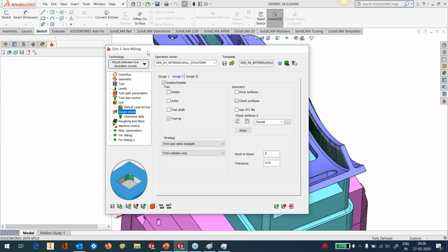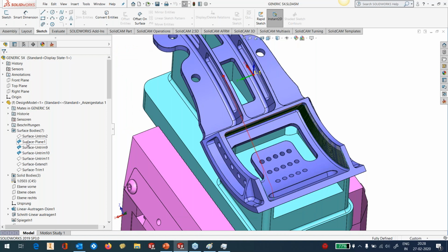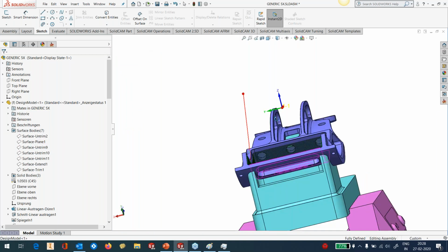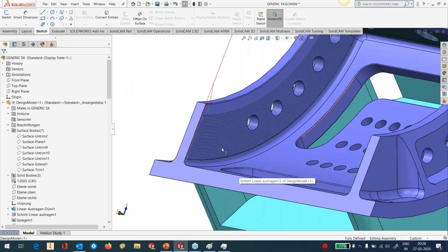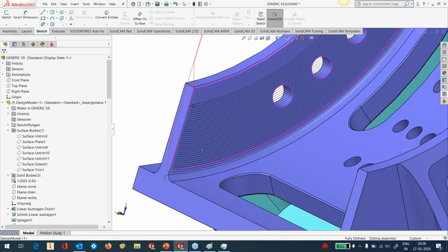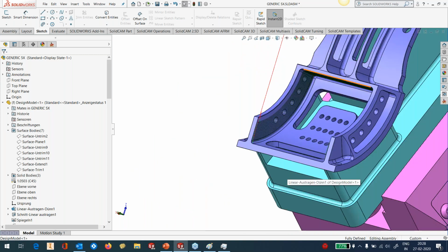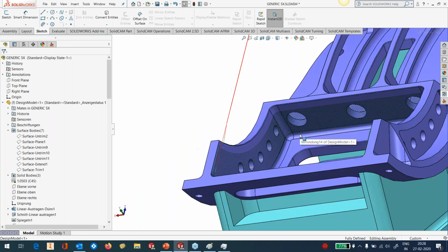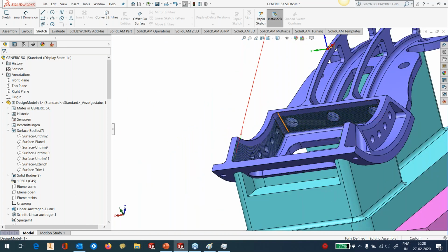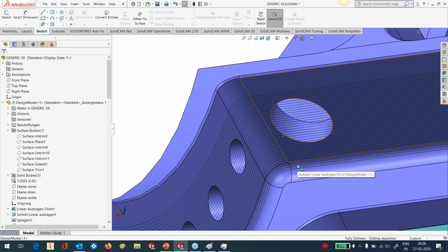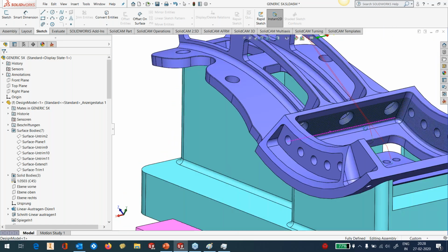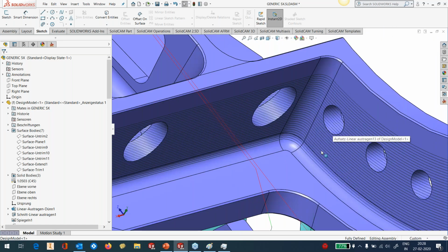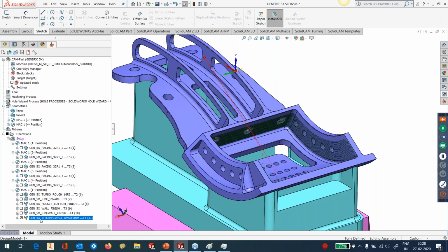Perfect. So we have a nice tool path. Let's switch off the surfaces that we opened up. And I have a pretty nice tool path here. Very nice entry. And you can see what happens even at the corners when it gets the collision and it does the auto tilting. You can see that even those areas have been smoothened out. Very nicely done tool path with a barrel tool. Okay, with an oval form tool, circle enders. This is what we have to call them.